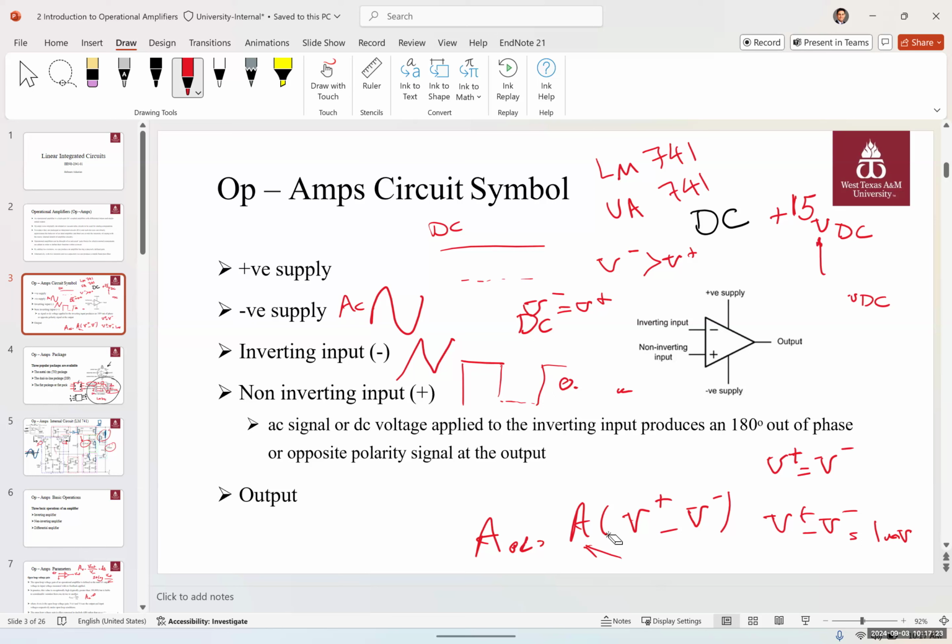It's a timer, actually, that has a motion detector. And that motion detector is connected to a relay or timer. And each time I pass in front of it, it resets that time. The reason it does that is that if it doesn't sense any motion or any person, we have different motion detectors as well. This is like an infrared one. Most of them are. The more accurate ones are infrared. So it usually detects heat from the body. So it won't mistake a car moving for a human moving or a cat moving. So anyway, we have different motion detectors.